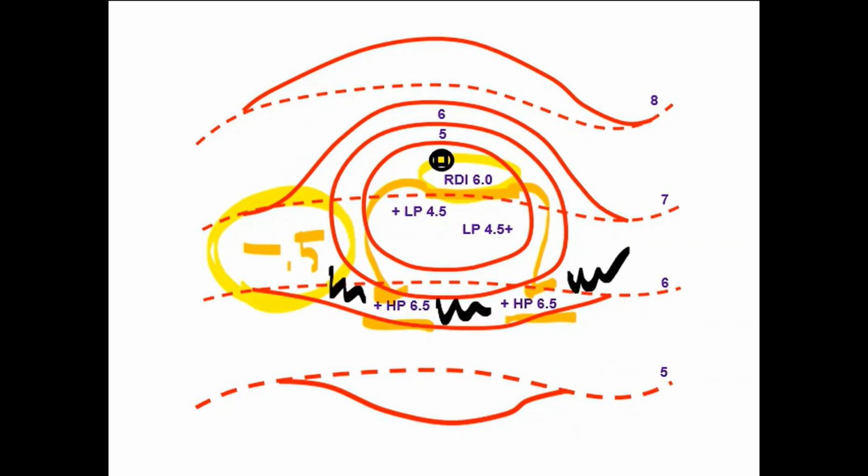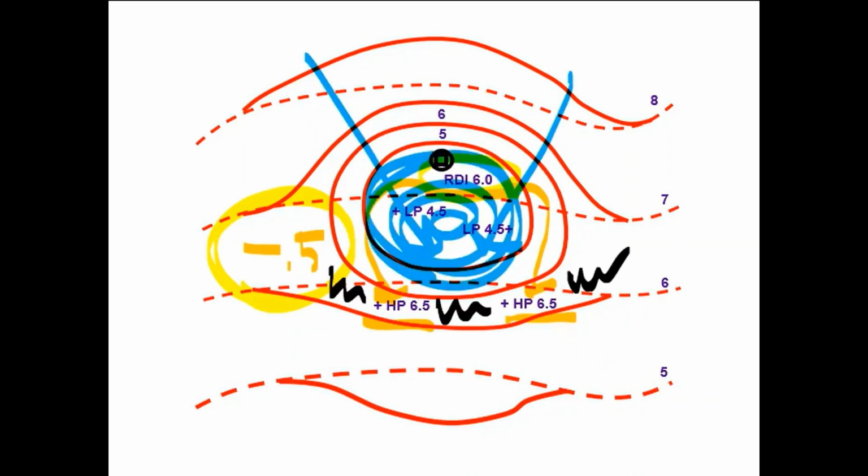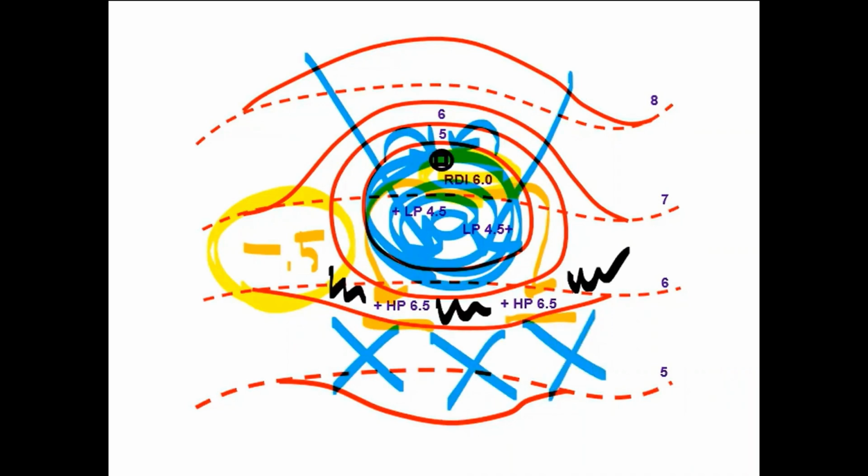What will happen then, of course, is that water will run into the system as it did before. The system will fill up with water. And when it gets to the elevation of the raised drop inlet, then the water will simply flow into the raised drop inlet and not flow downhill over the berm. That's very important, that we not allow the water to overflow the system and erode the bank. We want the system to be used so that the water overflows into the raised drop inlet.